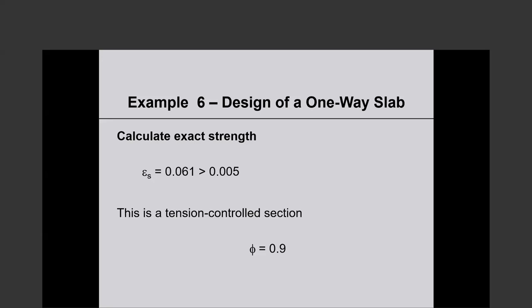Yeah. Without context, it's very difficult to say. Anyway, we do computer analysis. You will put everything into the computer, and the bending moments and things will be calculated at the face of the support anyway, whether it's the beam support or column support.